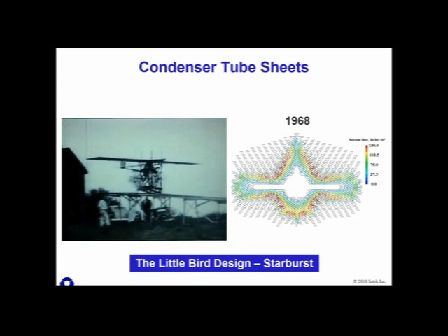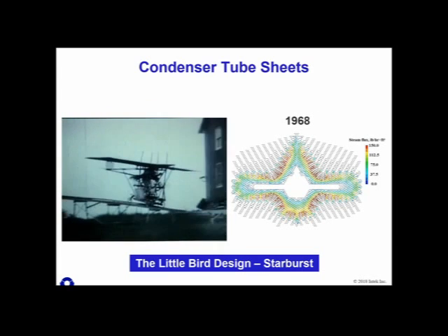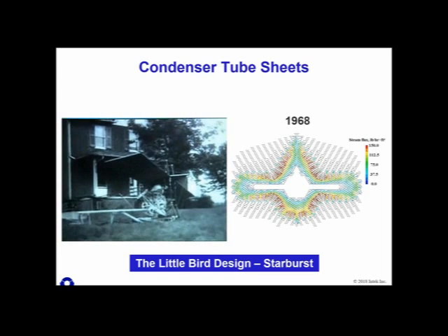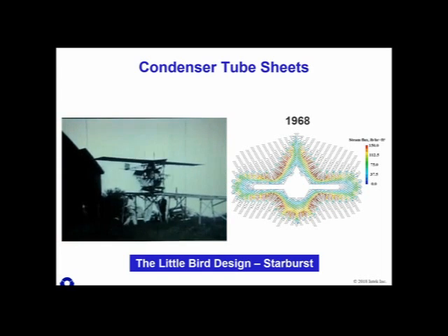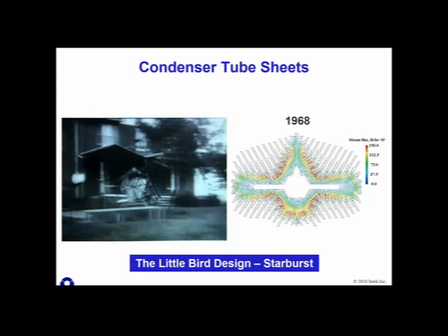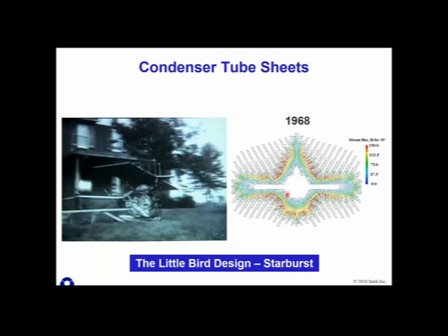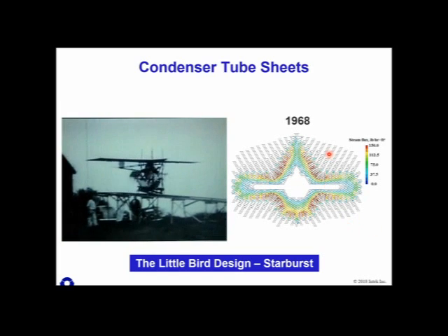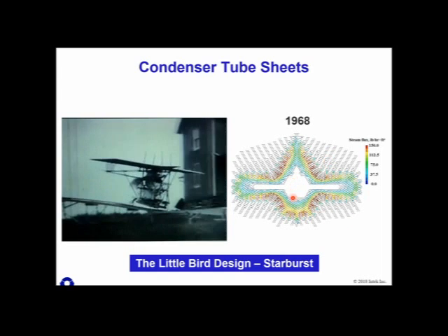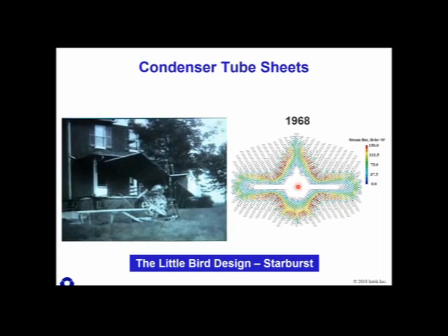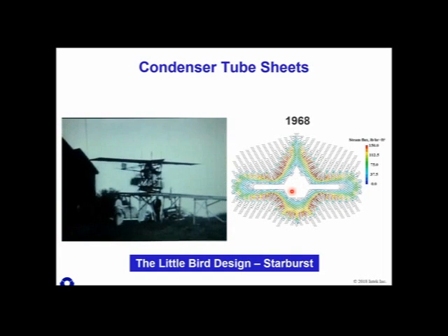Here's another design. This is the Westinghouse design. You would see designs similar to this coming out of Siemens and Mitsubishi nowadays. A very popular design. Westinghouse was very good at selling a lot of these. Some unique features are there is no shrouded air removal section here. It removes gases by a central pipe that conveys the gases down to the cold end.